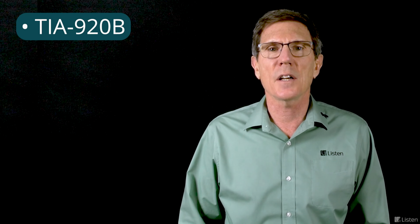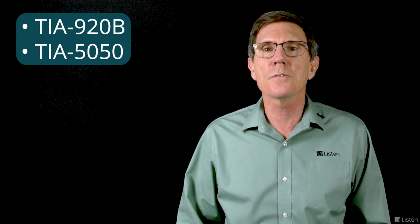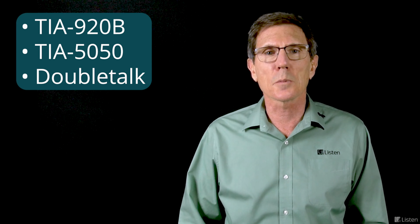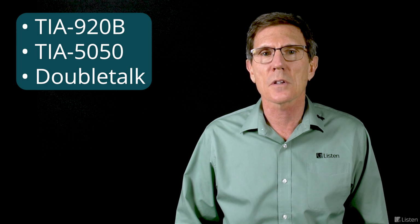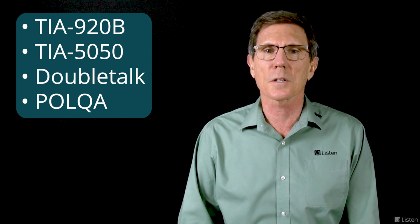In this seminar, we're going to demonstrate several communications tests that you can implement in SoundCheck on all types of devices. We'll start with the Telecom Industry Association TIA 920B that covers measurements for handsets, headsets, and speakerphones. We'll also show TIA 5050, which measures receive volume control performance, double talk for measuring echo cancelers, and Polka, a perceptual measurement of speech transmission quality.